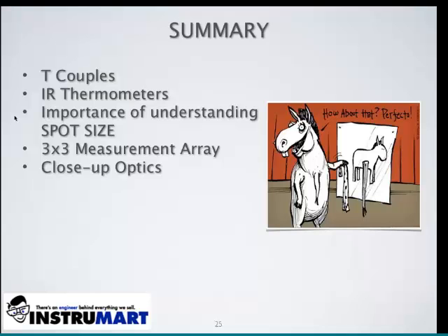Our thermometers are limited by the size that they can resolve. And the best that we could do was about 5 by 5 millimeters before we started to see substantial error in our measurements. But there are also some inherent limitations to thermometers as well, such as target alignment, knowing exactly where you're measuring, and this averaging impact, but also the fact that there is no input for reflected temperature produces some inherent limitations and errors.